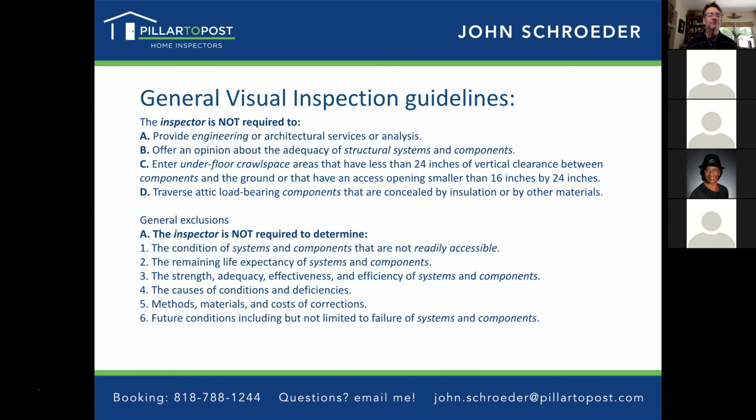Also not required to traverse attic load-bearing components that are concealed by insulation or by other materials. Also, the inspector is not required to determine the condition of systems and components that are not readily accessible. The remaining life expectancy of systems and components is not required to be determined.